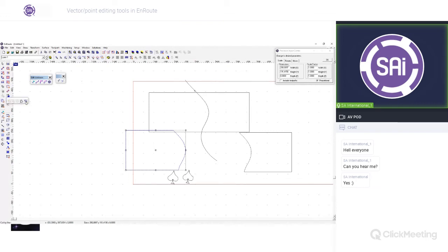So finally here, we also have the cut by line tool. If you cut through parts, it will simply make a cut where the line was. But if you have a closed shape and you cut through it with this, it will create two other closed shapes from it, as you can see right here.